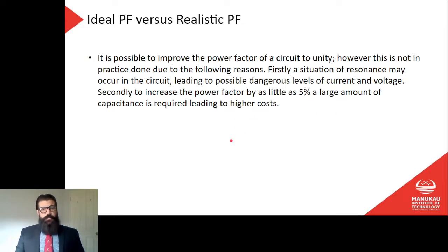It is possible to improve the power factor of a circuit to unity. Of course, it's possible. If I have the exact same capacitive reactance as I have inductive reactance, then my power factor will be 1. However, this is not done in practice due to the following reasons. Firstly, a situation of resonance may occur in the circuit, leading to possible dangerous levels of current and voltage.